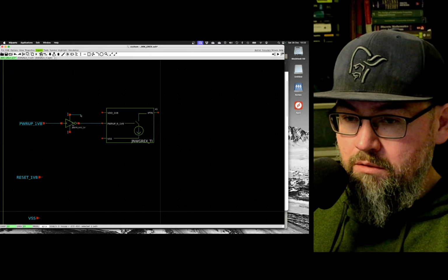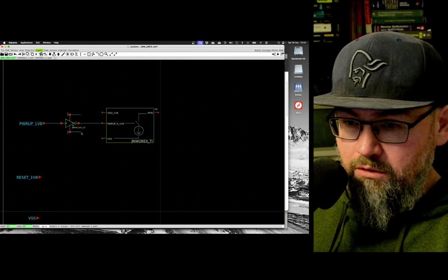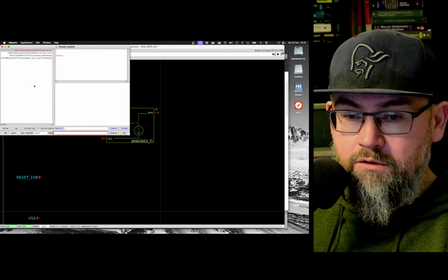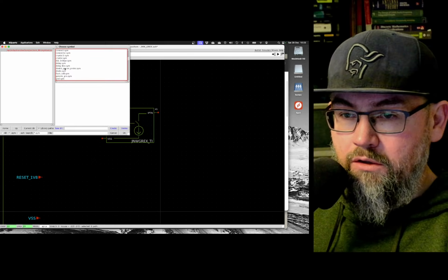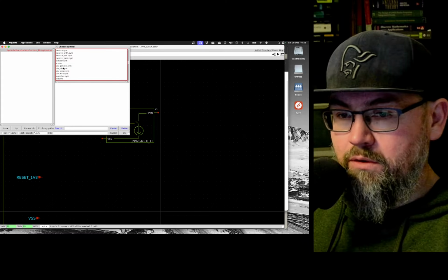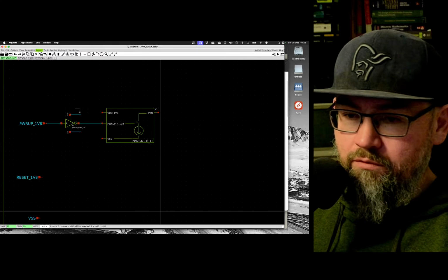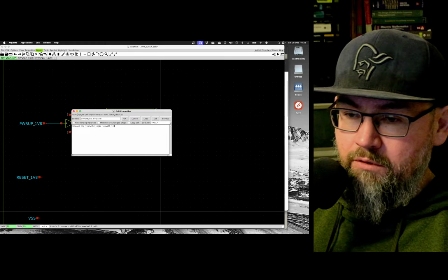And then let's put these in. So actually, I kind of like Shift I to find the lab wire. What I was going to say was I kind of like connection by name for powers. It just makes maybe a bit sort of cleaner schematics. So VDD 1V8.